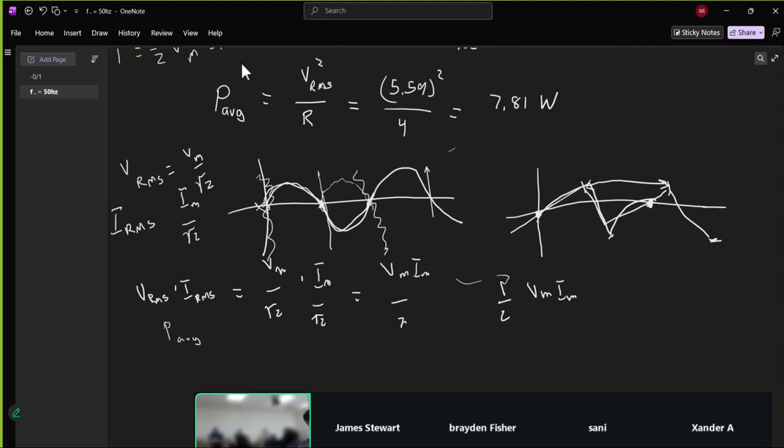Yes. Alright, so if I just gave the voltage an additional 5 volts of DC baseline, that would just be the VRMS that we already have, plus 5. Or we recalculate it, but pretty much that's it. Yeah, I mean, maybe. If it were DC, then maybe, but if I add 5 to something, I'm not going to get the same RMS plus 5 because of that squaring and integrating.